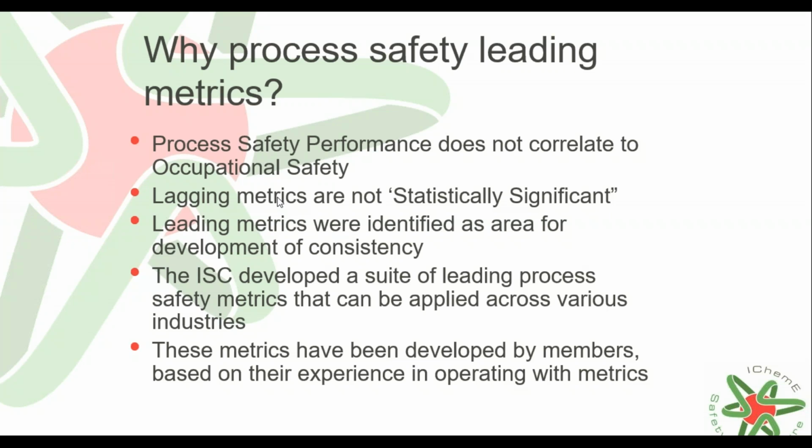So I guess there's no simple answer to the level of failure. Generally, the failure means something's gone wrong. If you obviously only have one failure and it's a random failure and the next time you test it, it comes good, then it might be more a fabrication or a quality of overhaul issue. So it really depends on a case-by-case basis of what the cause of the failure is, and if it's relatable to wear and tear and process conditions, or if it's more of an overhaul workmanship type problem.